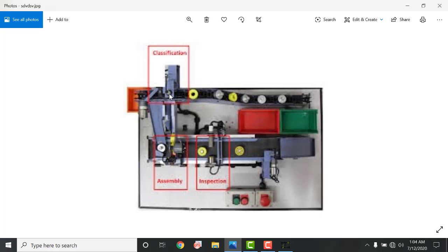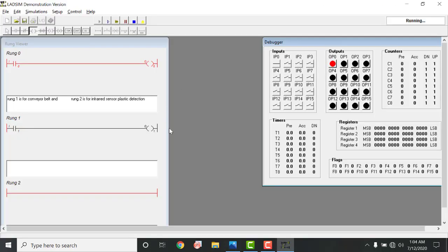So when both these sensors detect that metal object, they would send a command to this solenoid valve to shut off, which means they would let this metallic material bypass from that position, and the solenoid valve will not work in that case. So let's start for that.